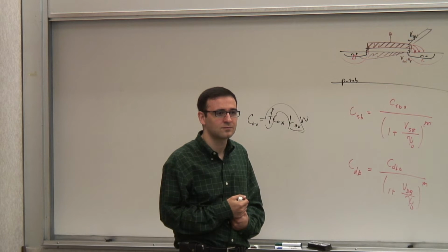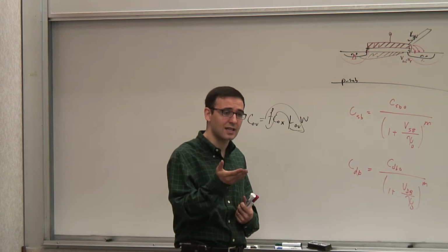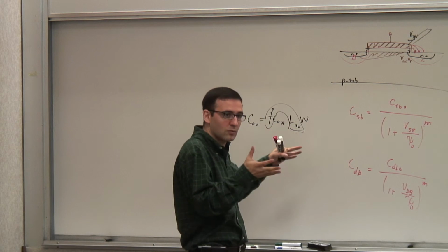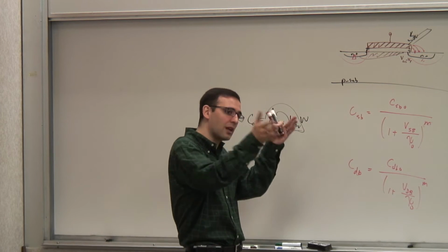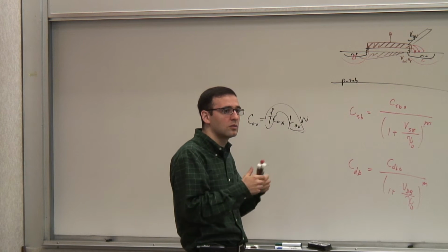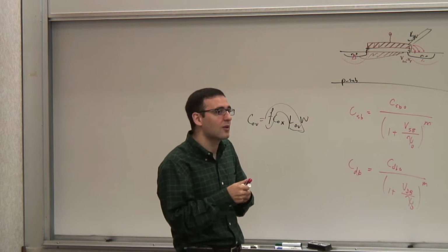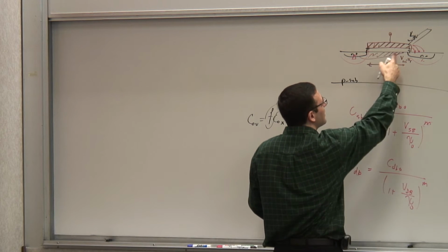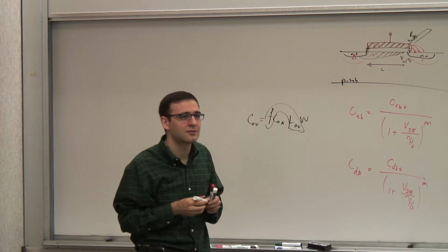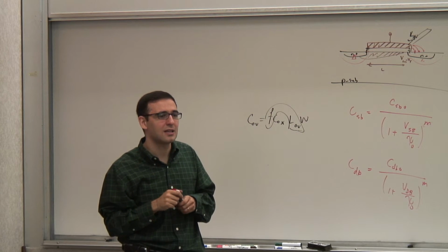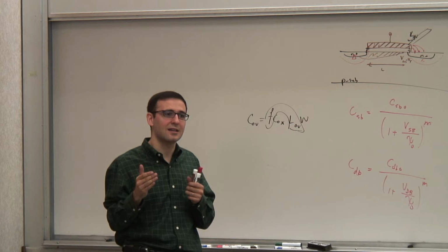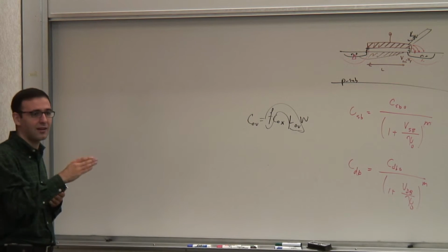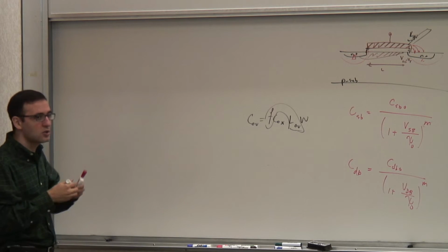Well, that's Cox. That's the gate capacitance per unit area, right? That's Cox, correct. But what is the total capacitance? That's capacitance per unit area. Times the length of the channel. Yeah, but okay, times the length of the channel. You said this length. Why? The charge is not uniformly distributed on this side, right? So if you want to do it accurately, it depends on where it is. Now it's interesting that you can actually calculate this exactly. So let's calculate. How do we calculate it?